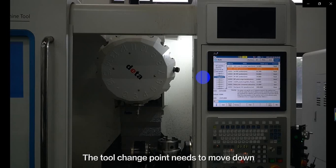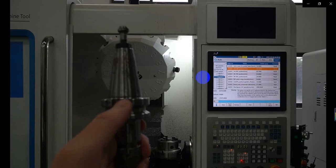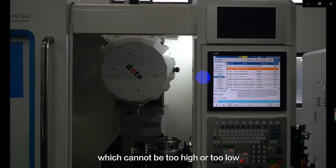The tool change point needs to move down the Z-axis solely in the manual mode when the tool magazine just stuck to this point of the tool. It is the best setting position of the second reference point, which cannot be too high or too low. After completing the settings, we need to fill in the tool heights into the second and the third reference points.